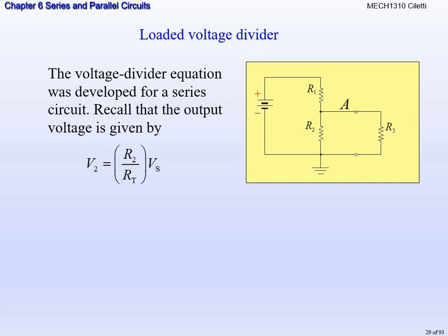These shouldn't be anything super new to you. This is because we talked about voltage dividers extensively in series circuits. This is how your multimeter works and how it gets the correct voltage reading. If we wanted to look at the output voltage across R2, remember, this is just review. R2 divided by the total resistance times the voltage source would give us that drop across R2.